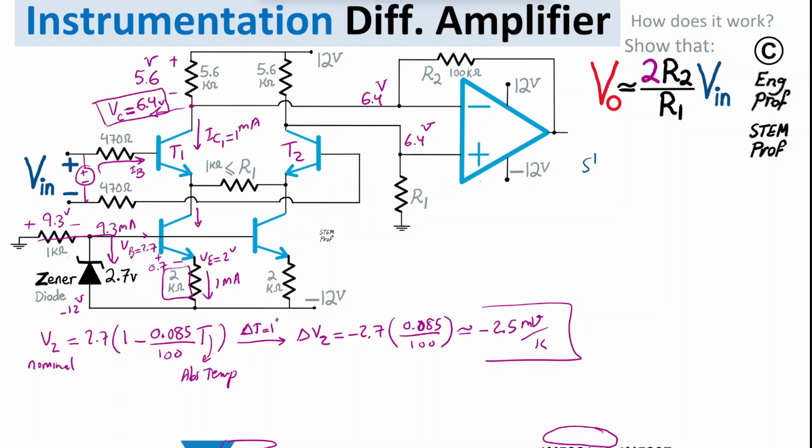So, from considering the Shockley p-n junction equation for the IV equation of the BJT transistor, we have the collector current equal to the saturation current times e to the voltage of base emitter divided by thermal voltage VT, which is roughly 25 millivolt at the junction at room temperature.